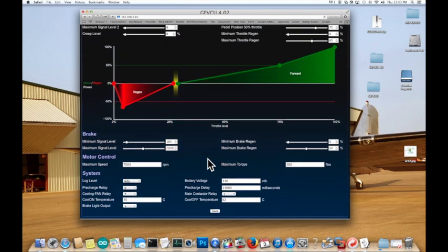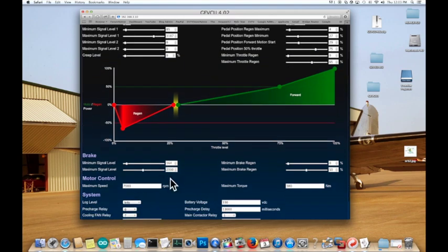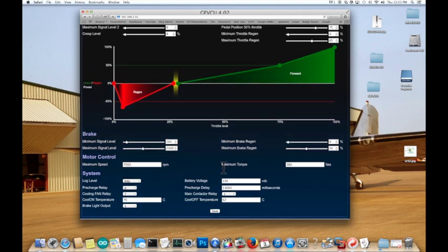What happened? Well, the software is looking at EEPROM for these values. We have the old values. We wrote a new value in, and that may have been at a memory location where one of these old values had previously been located. Things moved around in the EEPROM.